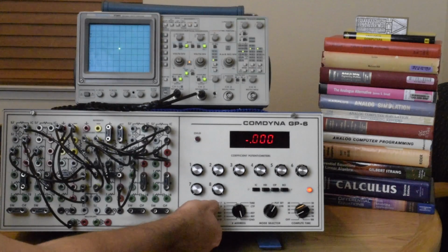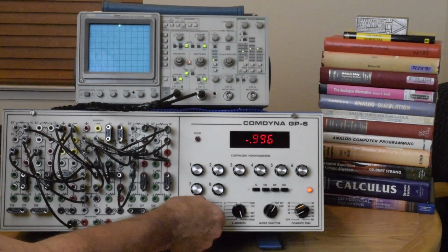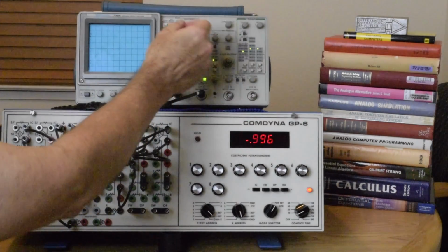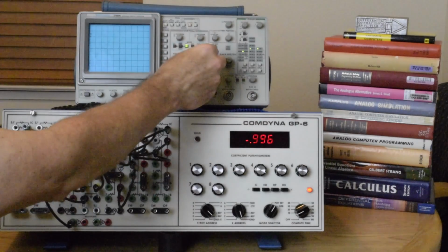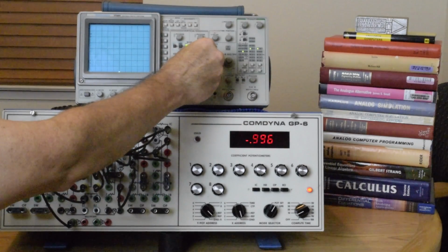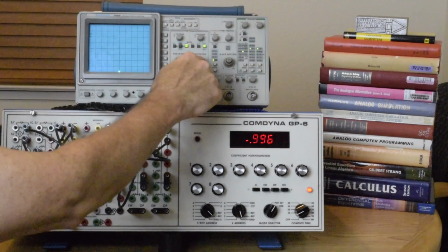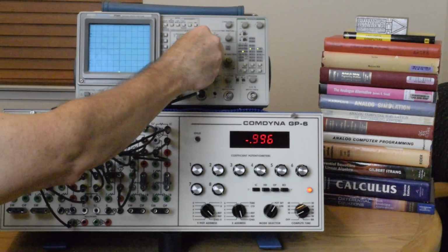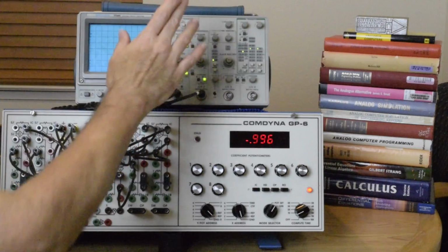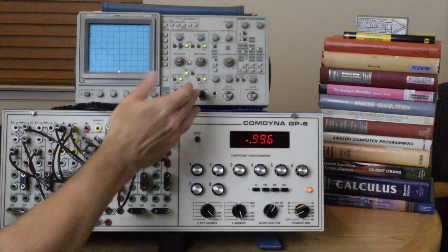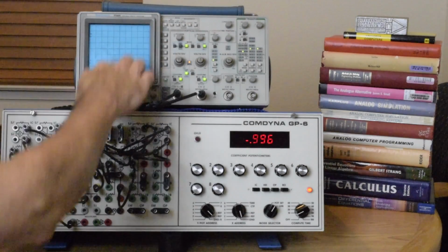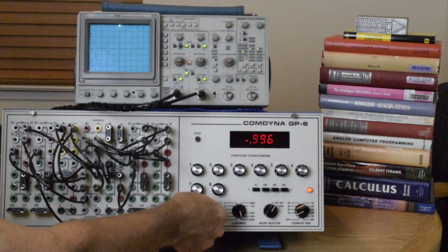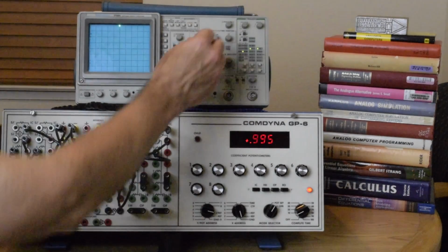Then we can switch this knob to the negative reference range and positive reference range. And if those are off, for the y-axis, we would adjust the Y calibration. So right now, the scope is technically not calibrated to measure volts, but what I'm doing is calibrating it against the reference voltage of the analog computer, so it will give accurate results as far as the output of the analog computer is concerned.